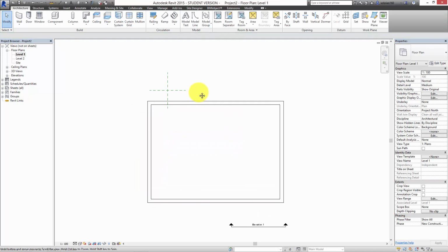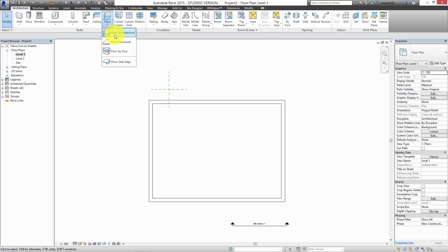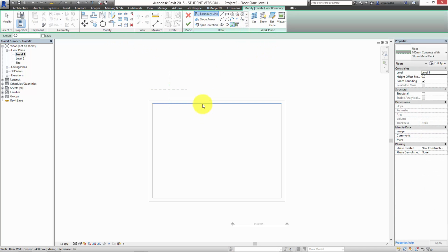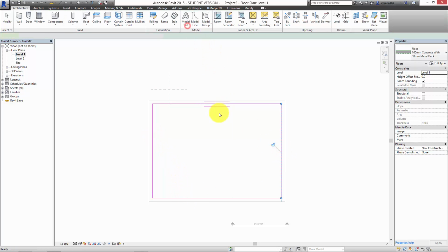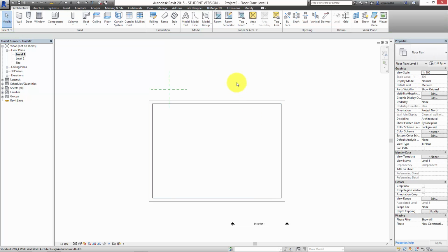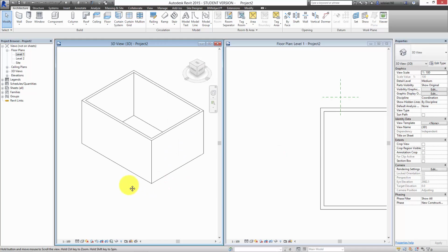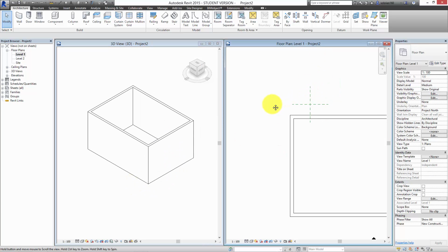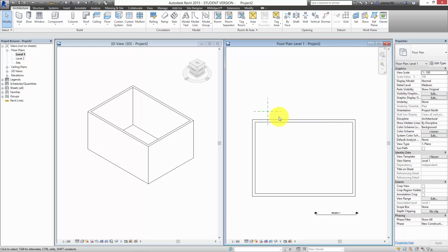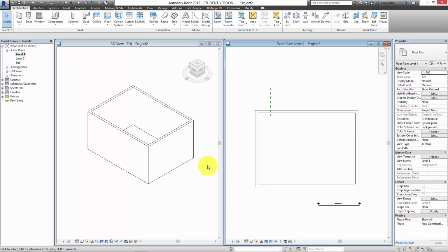And let's put in a floor. So again, I'm going to pick the lines. I want to be here, here, here, here. And let's put it on the screen at the same time. In order to get whatever drawings you have open, you can put them on the screen by pressing WT. WT is the shortcut for doing that. If you had 6 drawings open, they would arrange themselves on the screen, so you can see all of them if you press WT. Window tile, it stands for.